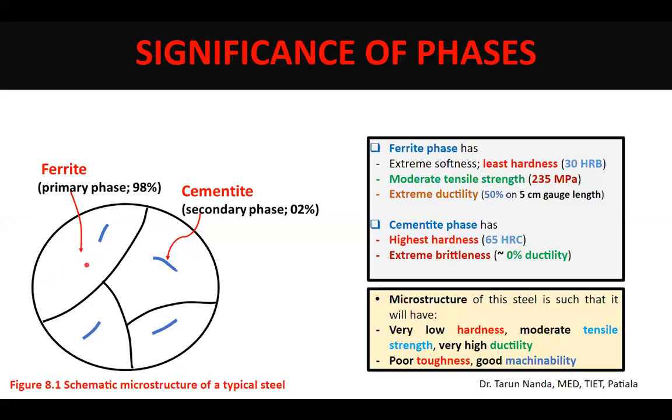On the contrary, if the cementite morphology was globular or of bigger size, so that it had ample cross-sectional area to bear the shock load, then it would easily have transferred the load to the primary phase before failure could have happened.